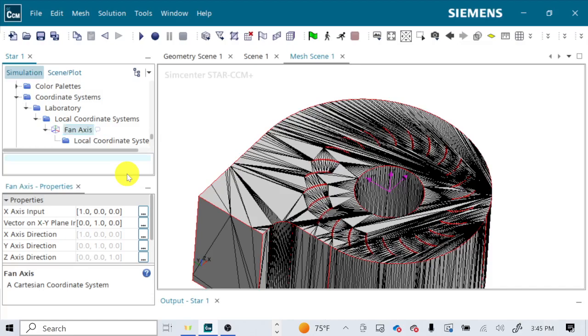You're saying it was a tessellation error due to the geometry. If we were to actually create the mesh for this and then do that, would it potentially be more accurate? You still have tessellation errors. Okay. So you have tessellation errors because these triangles that you're seeing right here are what define the surface. When I exported it from SolidWorks, those are the triangles it made. SolidWorks didn't say it's a circle. SolidWorks said it's a whole crap ton of triangles arranged in this way. That's what a tessellation error is.